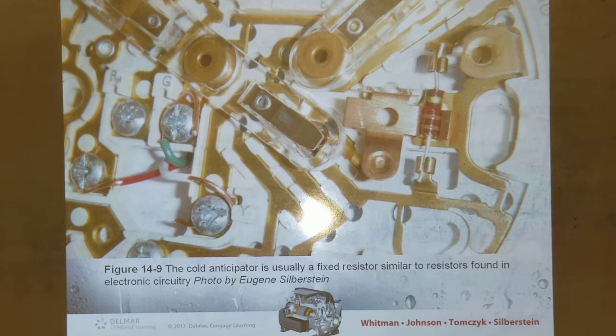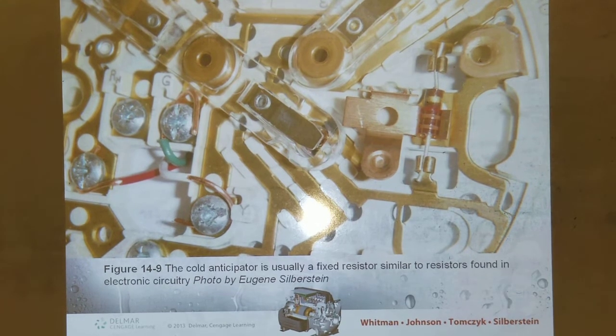Okay, so the cooling anticipator actually allows the system to stay on a little bit longer to get the system up to working conditions. The air conditioner, when it starts, doesn't just start cooling. The work that also needs to be done is dehumidification. So it has to be on for 10, 15 minutes, right? So this allows that system to come on and stay on a little bit longer.